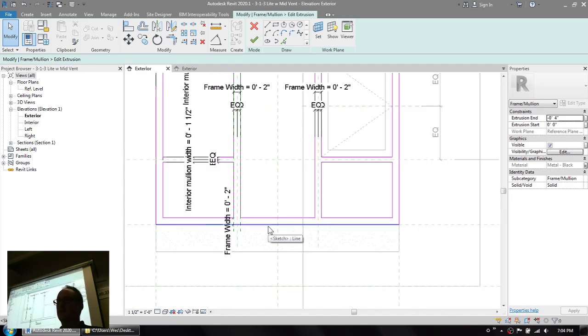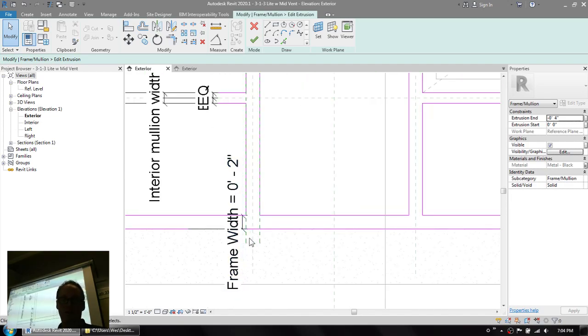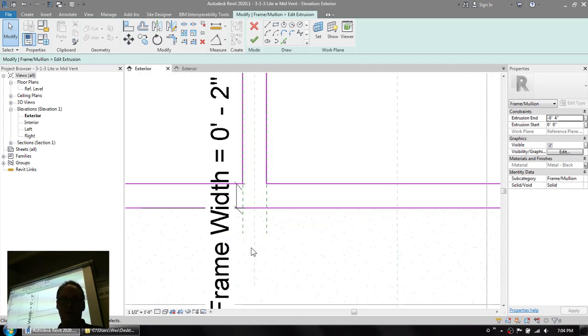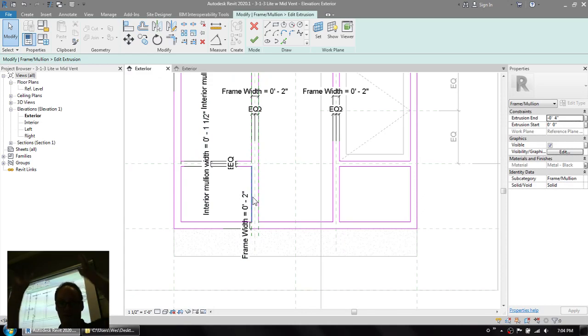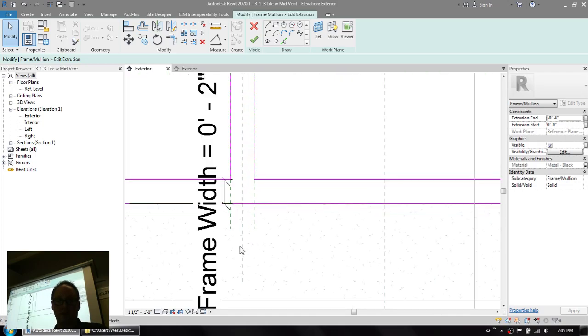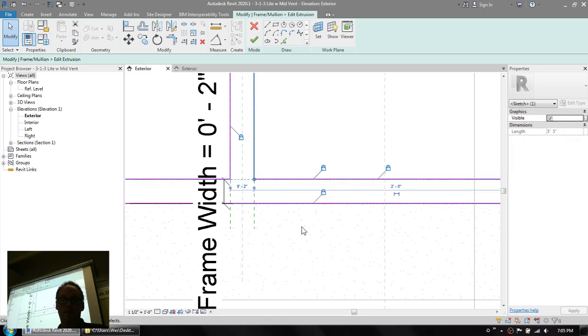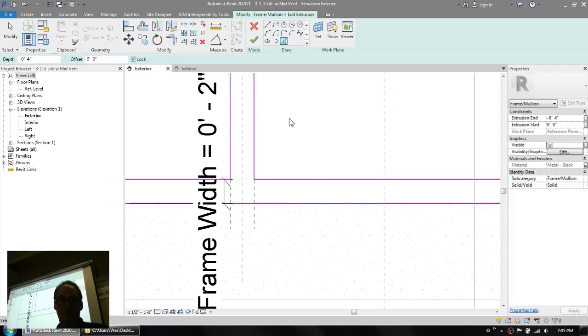And you'll see here now that these reference planes that I'm drawing, they're here inside the sketch, and I could dimension these reference planes back to this major reference plane that's outside of the sketch, the one that divides this window into 3 sections vertically. Those reference planes you can see because they're a lighter green, they're outside my extrusion. But these 2 here are inside. And I could take my pink geometry, my sketch lines, and pick the reference planes instead.